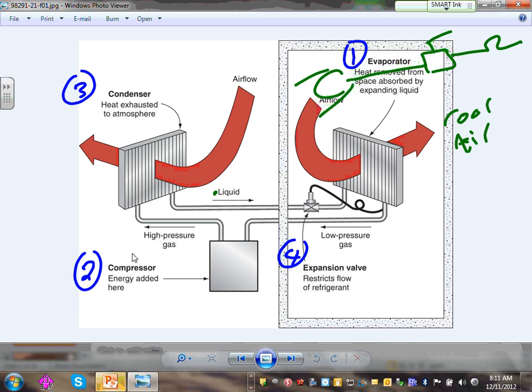Then when it picks up the heat, guys, then you bring it along. So then the liquid, because you're heating the liquid, turns into gas. Can you see that? Low pressure gas. Because the refrigerant liquid, as it collects the heat and stores the heat, changes state from liquid into gas. That's how they do it. So you enter as a liquid, you exit as a gas. Make sense? As a gas, a low pressure gas. Cool. And how did the liquid change into a gas? You collect all this energy, the heat, dump it right through the refrigerant, and it comes out as a gas.